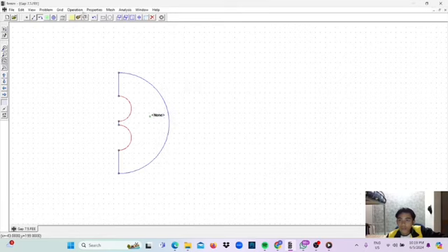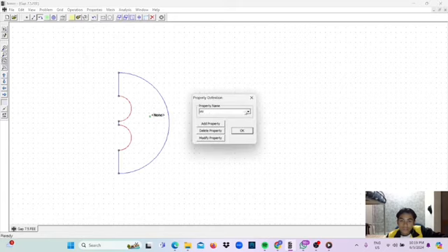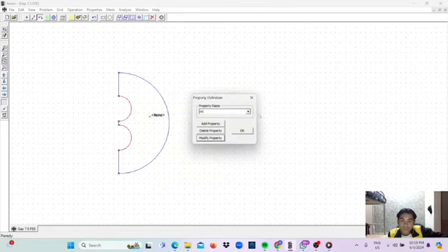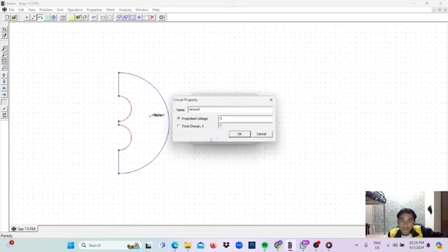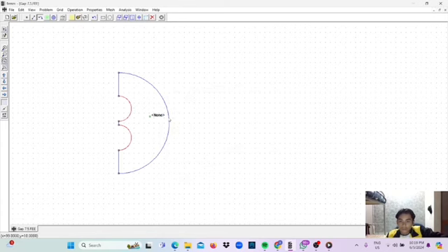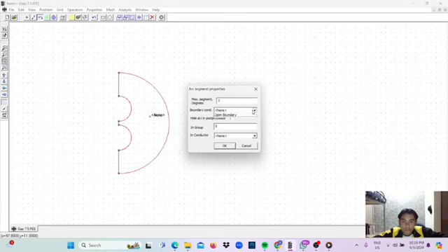and then click OK. After that, lastly we need to go to conductor, and then set the HV and ground element. For the HV, high voltage, the voltage for the 7.5 cm gap is 196 kV, and for the ground the voltage is 0, and then click OK. Firstly, set this open boundary.